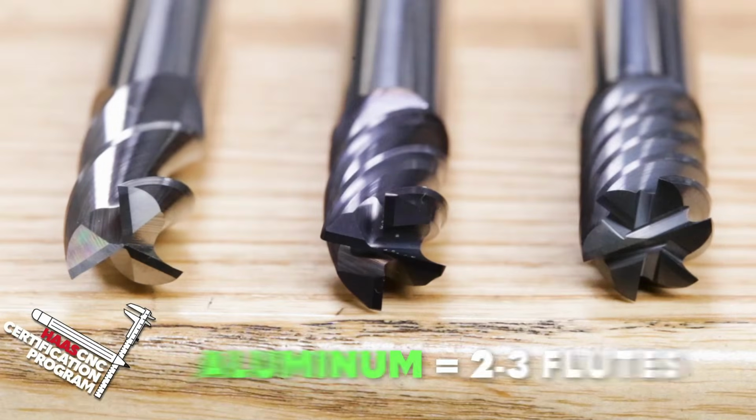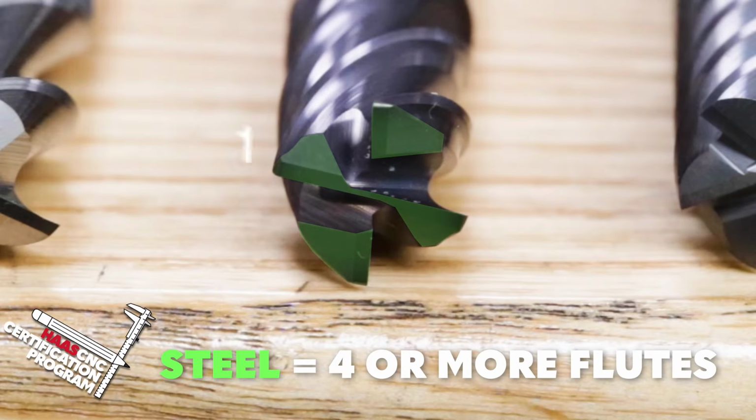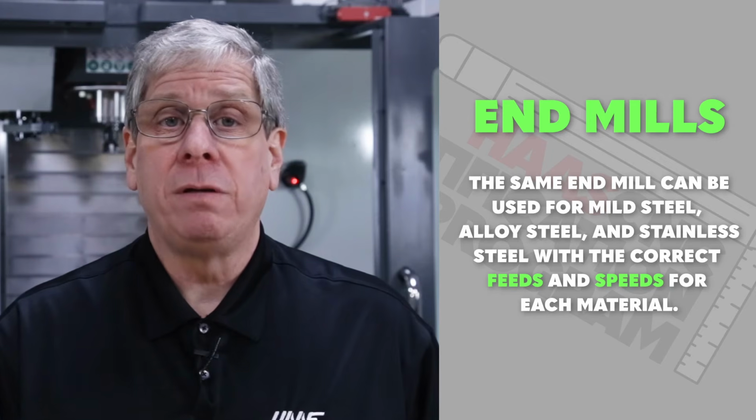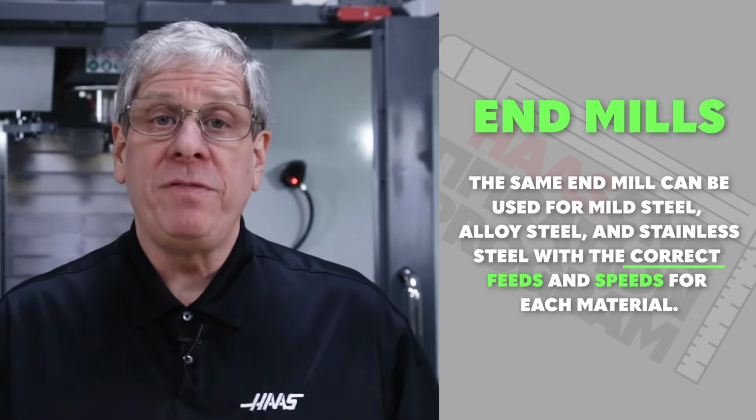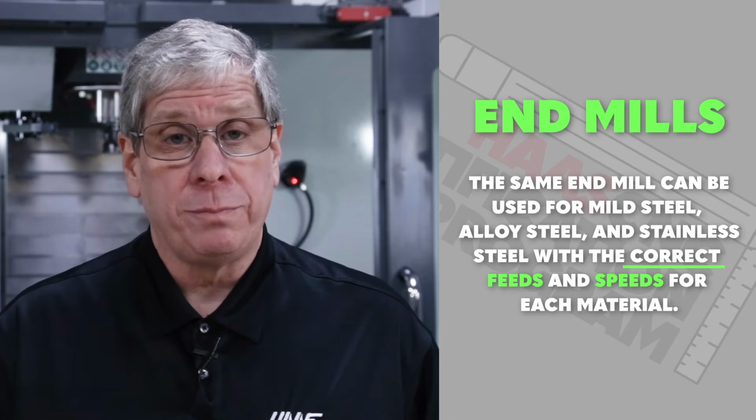Whereas end mills with 4 or more flutes are specifically designed to cut steel. These end mills are spectacularly bad at cutting aluminum. When it comes to end mills, you can basically use the same end mill to cut mild steel, alloy steel, and stainless steel. It all comes down to the correct spindle speed and feed rate for the given material.